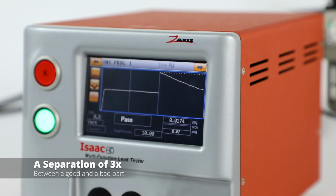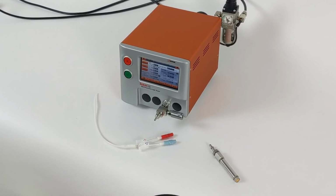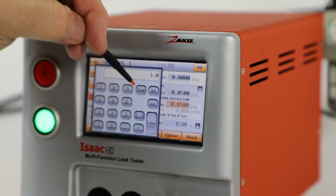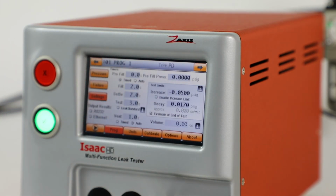So this indicates to us that we have a very easily achievable test that will be very repeatable, and then we can easily find pass and fail results. So if we ran multiple parts with the leak standard and got an average of those decays, we can now come back in and enter the new decay value that will cause a failure. So if the limit that caused the failure, the average, was 0.017, we could leave that value.